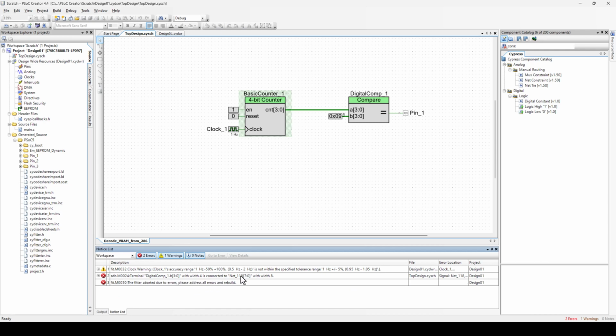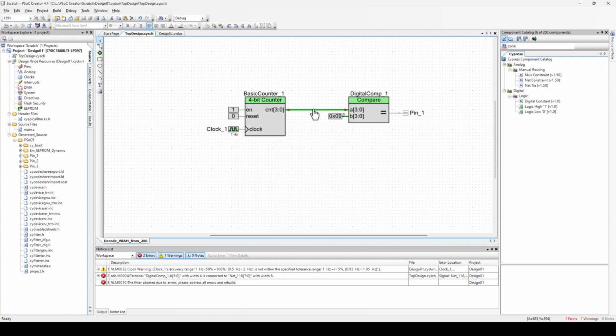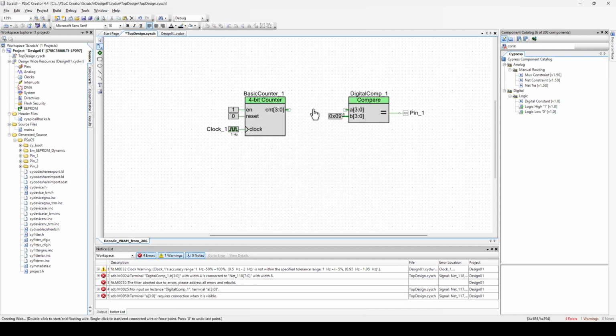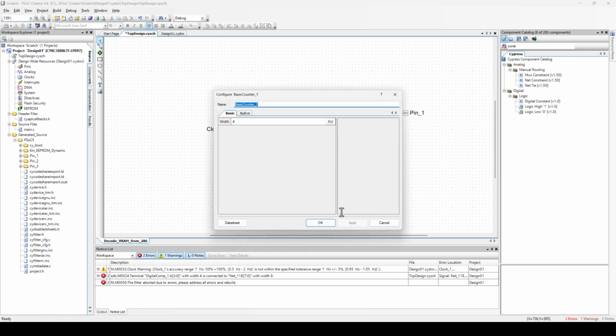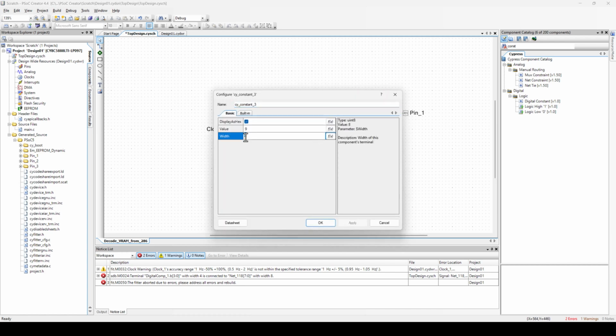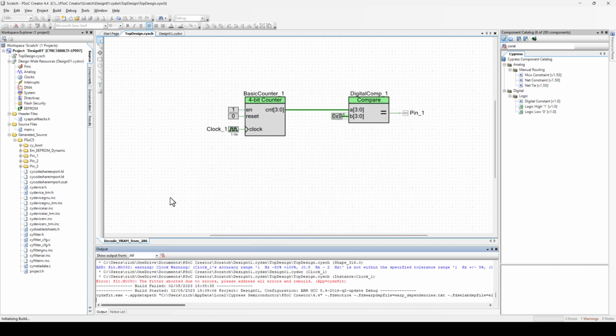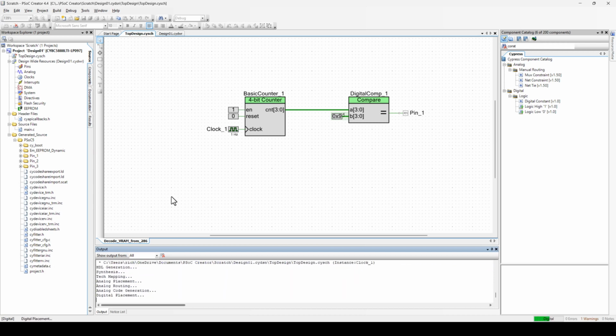And it says I've got something that's connected to a much bigger width, and that might have been this wire that I had previously connected. So I'm just going to delete that for a second, because that should be a 4 to a 4. This was a 4-bit counter, and this is a 4-bit there. Oh, this one here, I've got to tell it it's only a 4-bit constant. And let me try that again then. So I'm going to go through here and try this again.